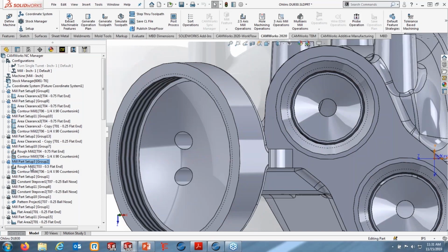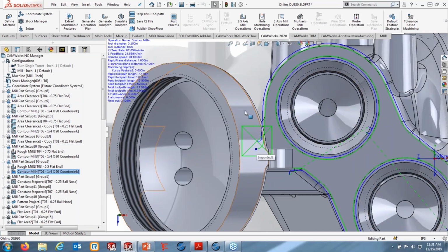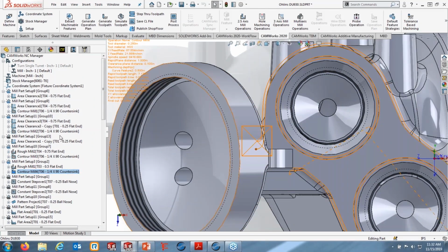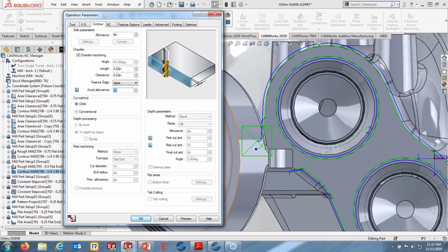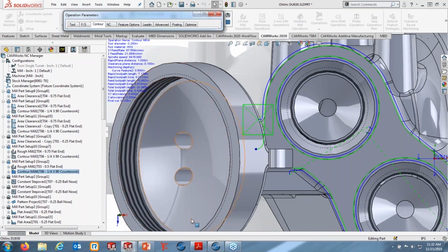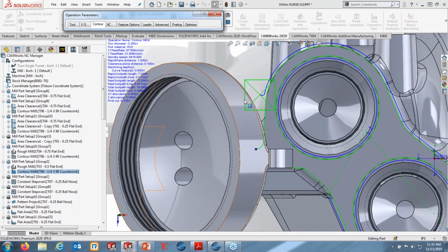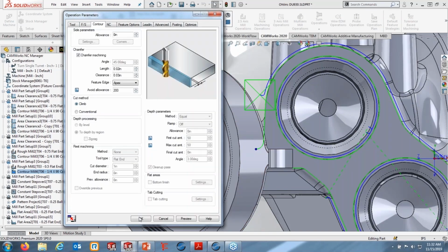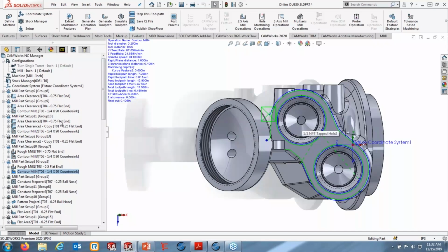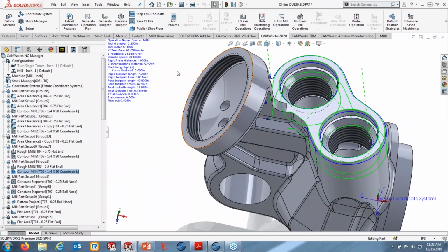But in this case, I can't get to this. It's going to gouge this top edge up here. I can always come in and adjust this avoid allowance, so I can crank that up and say, okay, maybe make it 100%, moving it away from the ends here. Maybe I need to go a bit more, 200%. So I can shift it along and move the actual point so I can do it, or I can just redefine that bit of the thing with a sketch if I need it to as well. So another great new enhancement that they did, just to quickly go and deburr parts rather than spending hours putting in chamfers wherever you want to manually, basically.